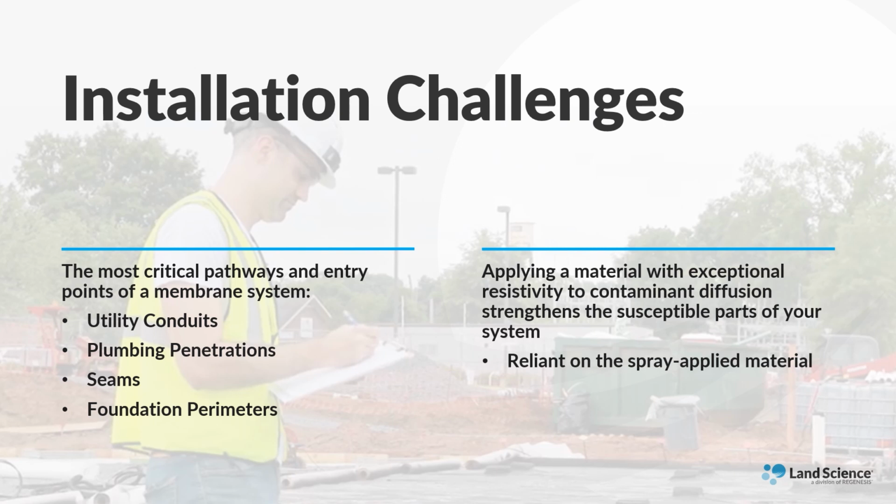In some cases, we can simply use some barrier material and spray, while in other situations, we recommend using a trowel grade version of our NitroCore that's called NitroCore Detail. NitroCore Detail has a thicker consistency, similar to peanut butter, which actually allows the applicator to fill small gaps. This is one of the best solutions when dealing with a large cluster of pipes. Using the correct material will strengthen those susceptible points in the system, and most importantly, provide a tight seal at all penetrations and then pass a smoke test.